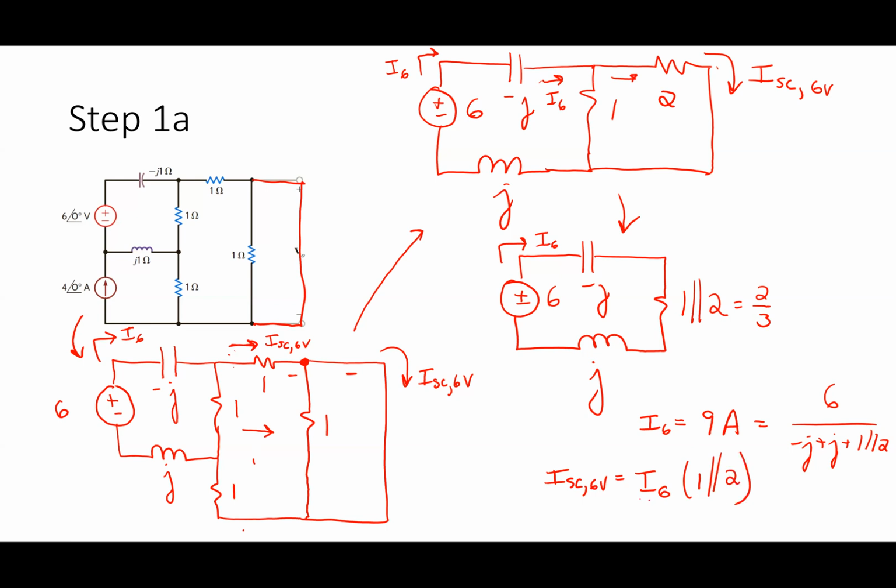And then to find the current, I divide by an impedance. Which impedance? The 2 ohms. And if I do that, I work out to 3 amps. Technically, that's with an angle of 0 degrees, it is sinusoidal after all. It's just to say there's no angle or a 0 degree angle. Okay.